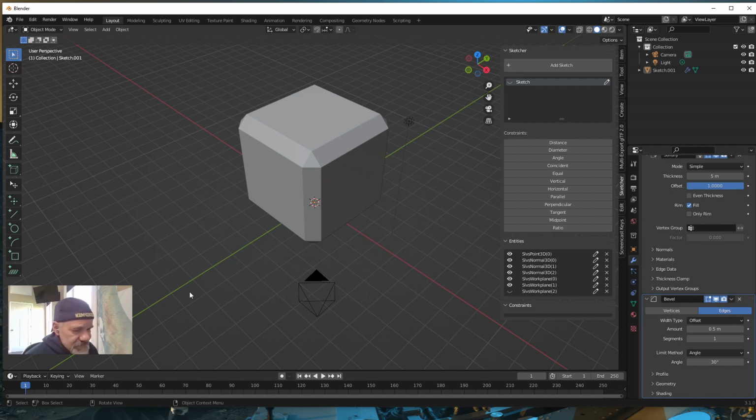All right, so we're going to add a new work plane selection. Remember, when we first did our object, we only had 3. We had the horizontal and then 2 verticals, right? We're going to add a new one that's at the angle of this face.